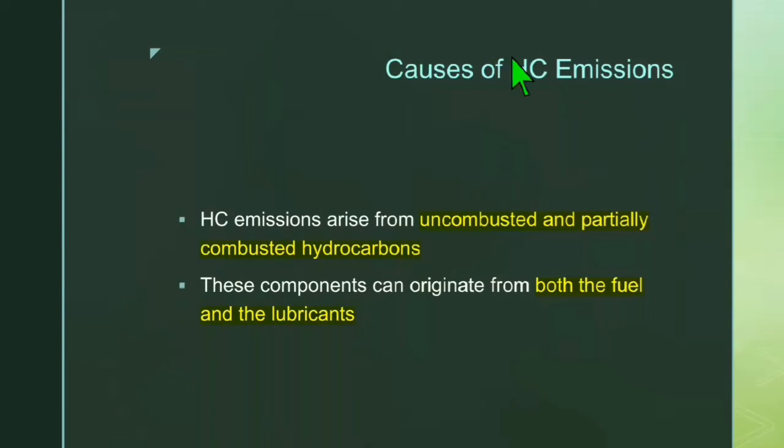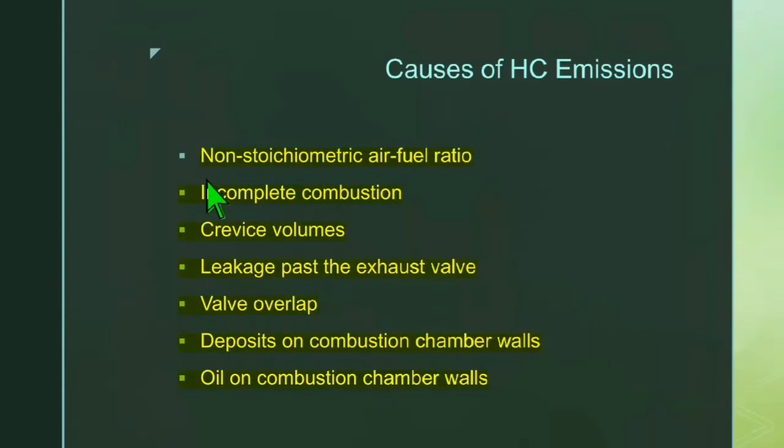Causes of hydrocarbon emissions. Hydrocarbon emissions arise from uncombusted and partially combusted hydrocarbons. These components can originate from both the fuel and the lubricants. Causes include non-stoichiometric air-fuel ratio, incomplete combustion, crevice volume, leakage past the exhaust valve overlap, deposits on combustion chamber walls, and oil on combustion chamber walls.